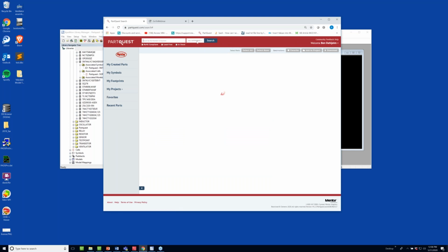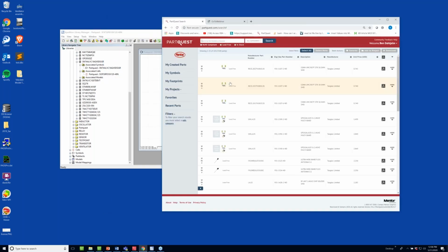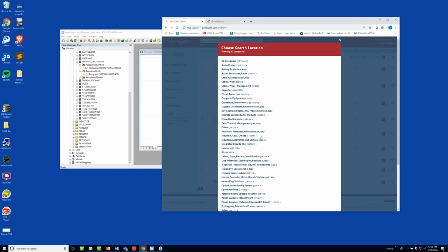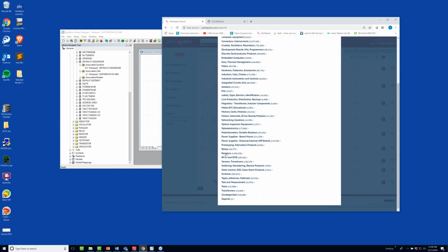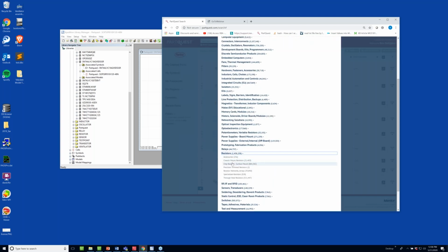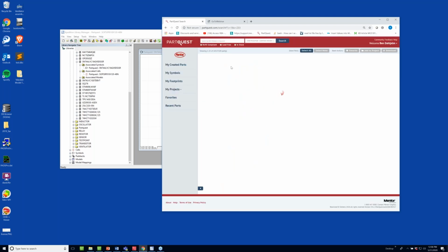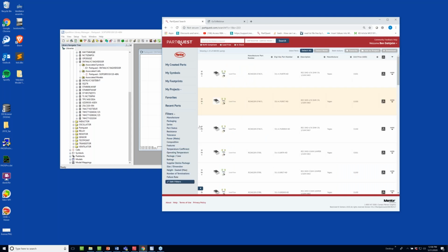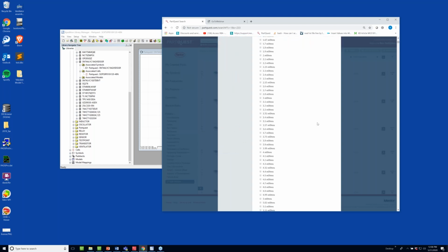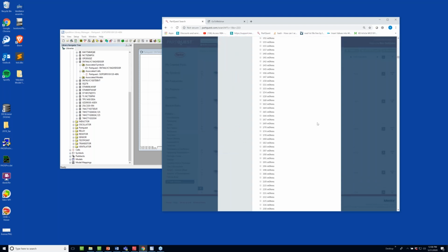It has a simple search mechanism there. It'll take a second to load. When you get this resistor, you'll get several results, and you may have to filter down those results. So I'll look for resistors. I have over 1 million matches. Let's do surface mount. You can narrow down this result until you find a part that matches the design intent. I'll even look at resistance, making sure I only have 10K in here. And the list goes on.